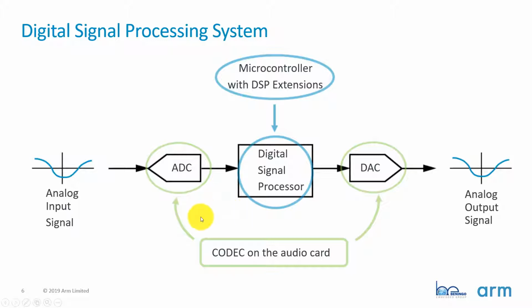If you do, especially if you're working with audio applications, you'll usually use the I2S interface to easily interact with those devices. So you'll use I2S and maybe I2C as a side channel to communicate with and control the particular IC. Those are a couple of examples of different ways that you can build up a system if you're going to be doing some digital signal processing.